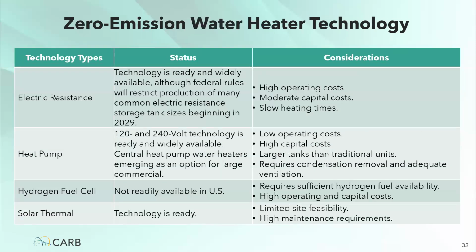This slide describes some examples of zero-emission water heater technologies, which are also applicable to pool heating. Electric resistance water heaters are available and serve a wide variety of residential and commercial building types, but typically have high operating costs and slow heating times, and federal rules will restrict production and importing of many common electric resistance storage tank sizes in the United States beginning in 2029. Heat pump water heaters are also commercially ready and widely available.